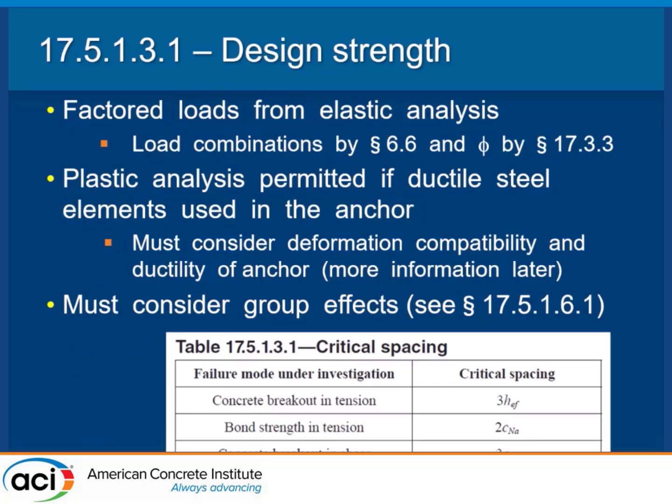Other things is the loads used from elastic analysis. Yes, you can do a plastic analysis. There's a lot that goes into that, but you need ductility in your anchor groups. And one thing I'm not going to talk at all about today is critical spacings and edge distances and things like that. Those are basically spacing limitations you have to live with.